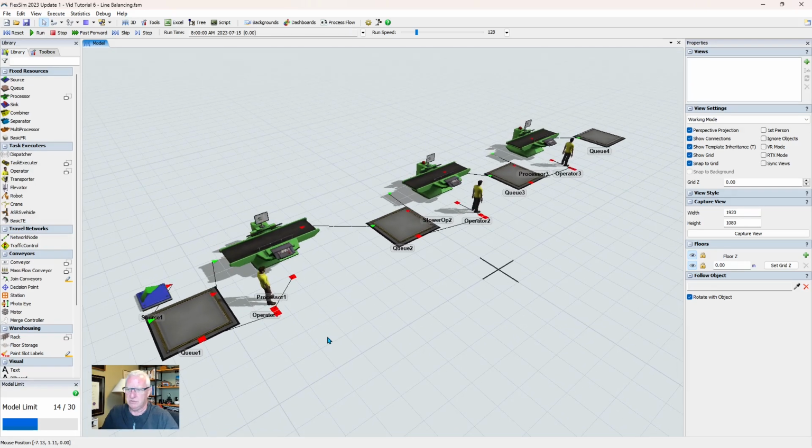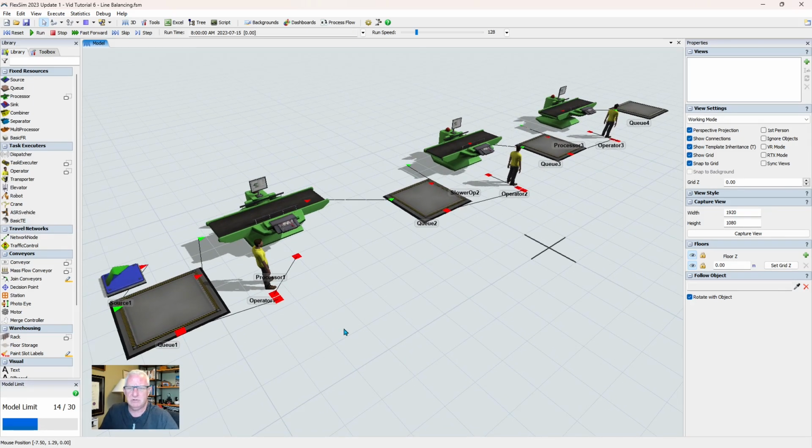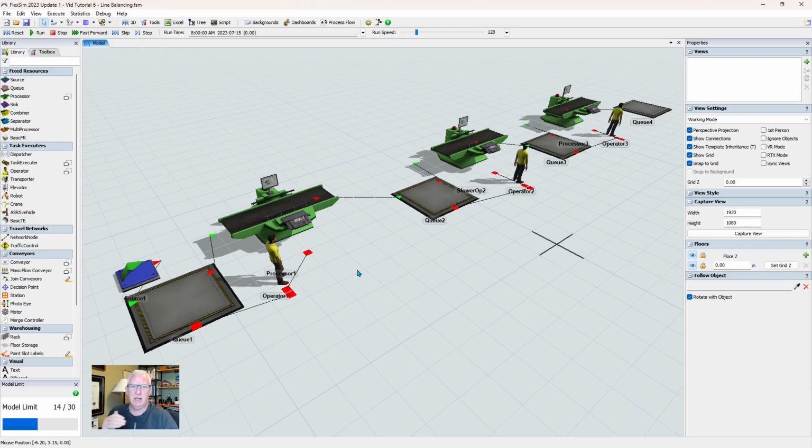Of course, in the real world, and if you're a lean practitioner, we would look at cycle time reduction or setup time reduction and trying to find other ways of reducing the effort, improving the value add output. But let's say for now that we can't actually change the setup time and cycle time of the machines. We can, however, control our supply rate from the source.